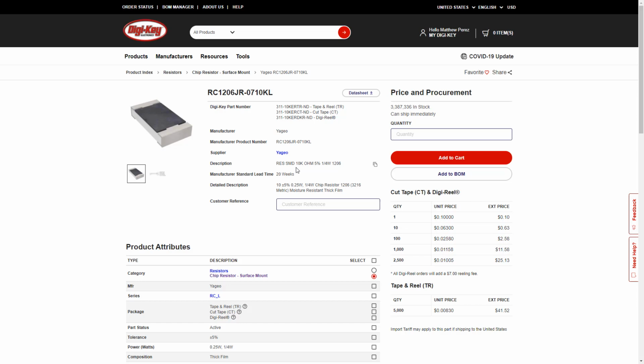Now, when we look here again, what we're doing is we're taking this surface mount, this SMD or SMT, sometimes it's one way or the other, and it's a 1206 package. Now, it's a standard package. Again, metric is 3216. And what we want to do is understand what that actually means. So when we're talking about the 1206, it's a standard size, it's a standard pad layout. This is generally done with a 0.9 millimeter by 1.6 millimeter pad, and there's 2 millimeters of space between.